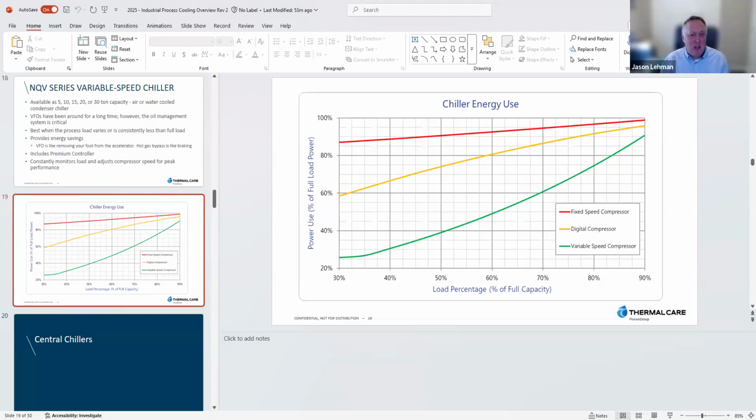And you don't have to bang compressors on and off and stage compressors, where maybe it drops 5 degrees below the set point, compressor bangs off, goes 5 degrees above the set point, compressor bangs on. It's just turning on and off for years, which can shorten the life of the compressor. It's kind of like running your car and slamming on the brakes in traffic. I'd much rather just run at 55 miles an hour and cruise along and hum along like that.